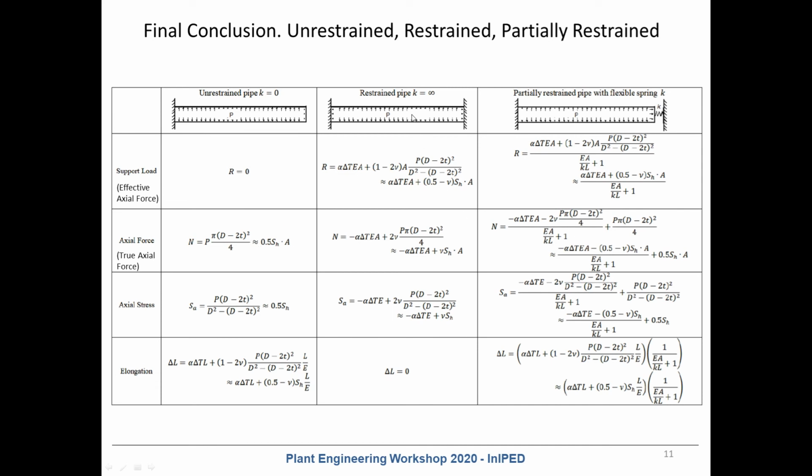For restrained pipe, the axial force is calculated using this equation, and the support load is calculated using this equation with additional force from the end caps.